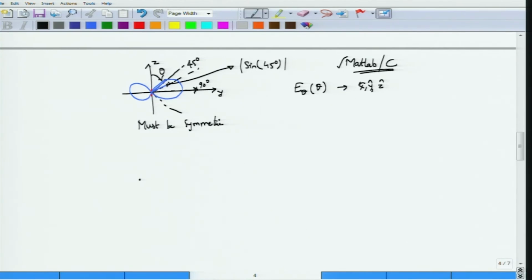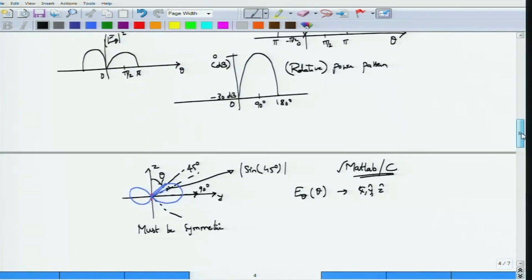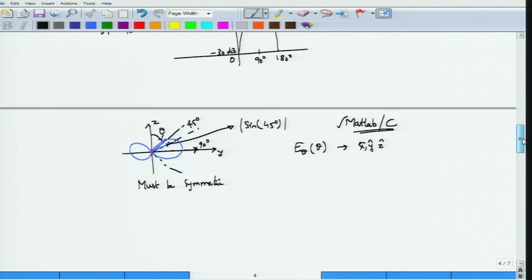So we have all these different ways of writing the antenna pattern. It's not probably very important for us to go into all these different patterns, but keep in mind that you can plot both power as well as intensity. If you were to plot the power or intensity, the intensity pattern would also look like this. Sorry, it has to be the same thing, but it would be much narrower than what you have, because this is sine square of theta magnitude.